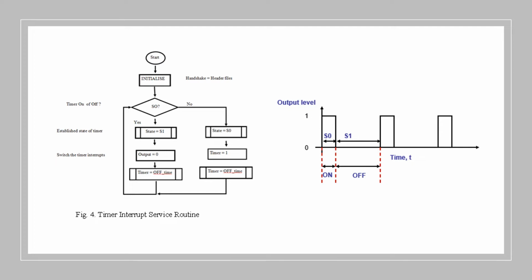In the PWM interrupts, timer 0 and timer 1 are used. Here we see a flow chart about how each of those two timers would work to generate on and off times. And this is coded in as cyclic duty in the interrupt of the developed software. So here we see the timer interrupt service routine.